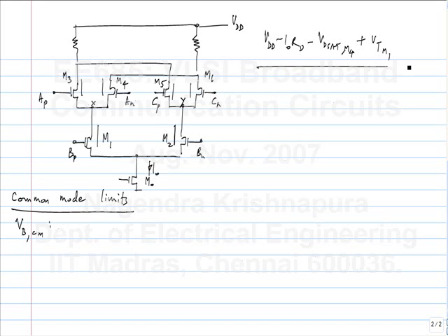How did you get this? We have to take into consideration when the okay. So for that we have considered that the total current is flowing out. No, this is all fine. Okay, this part is fine. I only have a question about this. How did you get this? Yeah. See, the VD sat is something that is a limit on the drain source voltage of the transistor. It's not the drain source voltage that you see all the time, right? So it doesn't have to be VD sat. Okay. So the condition is something different.